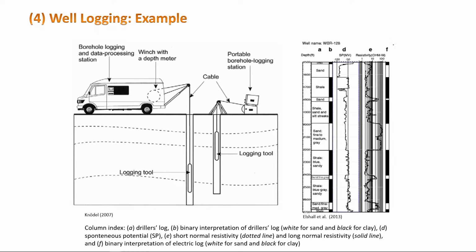For example, with resistivity, when you do borehole resistivity, there are two types. One is called short normal. Short normal might give you what is happening up to here, with a very high resolution. And then you have long normal electrical resistivity. Long normal electrical resistivity might show you up till here, an image of all this section, but with less resolution. So in addition to the surface geophysics, like the ERT, where you put 4 electrodes or 48 of them, you can also do borehole geophysics.